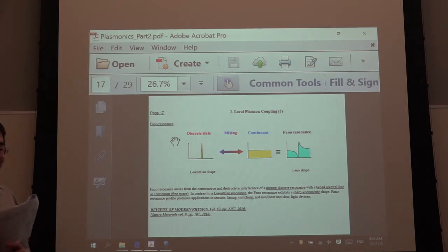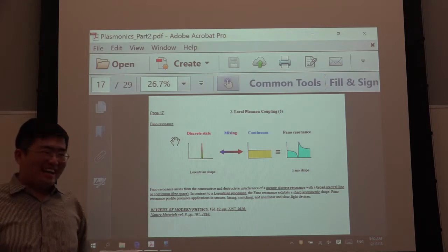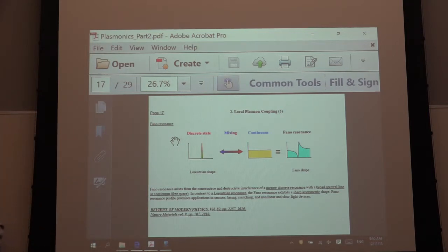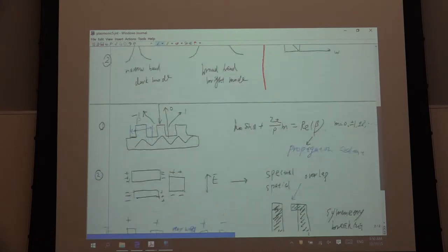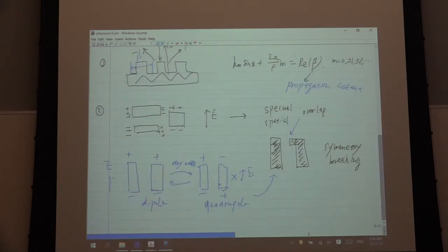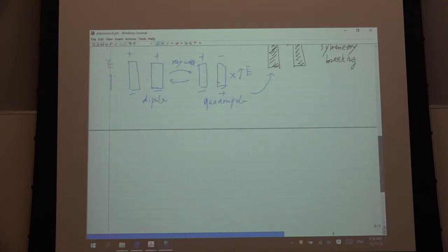Wideband is actually not that wide, just comparable. So they give different names. You have Butterworth, which does not have zeros, and you have Chebyshev, which has zeros. You can convert the transfer function between them even with the same type of filter. So how do you define the case for exciting the Fano resonance in microwave? You excite from one side, you receive it from the other side.